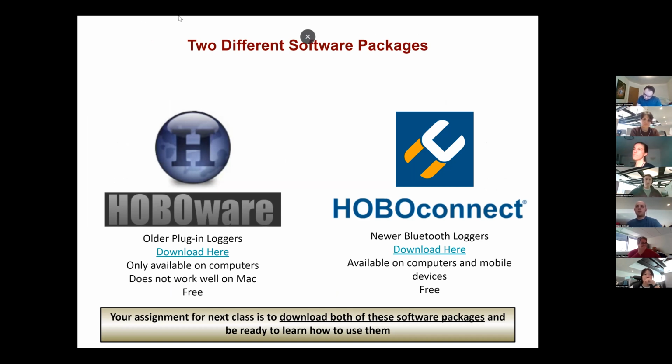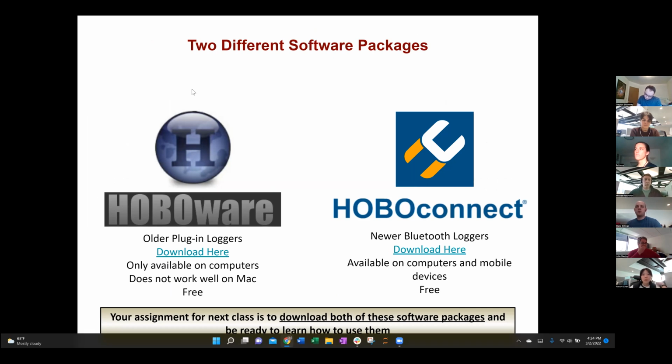Just a note for all the new students, 2 weeks ago we did the really new cohort. If you remember, we looked at nameplates a few weeks ago. On the nameplate for lots of machinery is a full load amps, or an FLA. That's a good place to look when you're looking at the size of a CT to use, but we can talk about that in a bit.